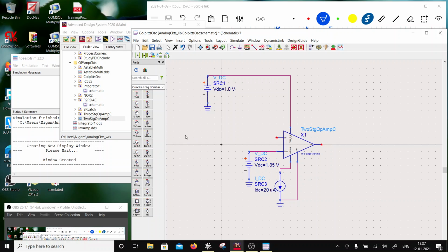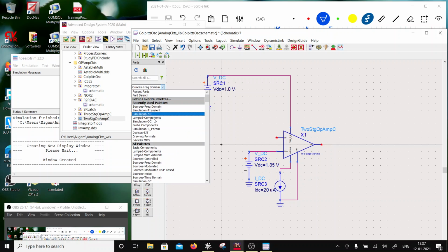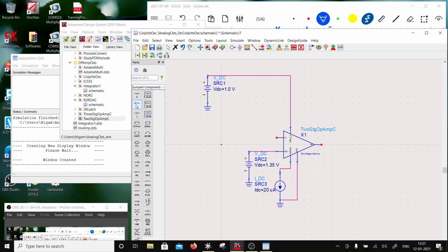CLC. So I'll go here to CLC. So I'll go to lump components. I'll pick up a L, and this L depends on 1/2 pi root of LC. That's how you are going to do that. So L I'm going to keep as 50 microhenry, and I'm going to give a certain loss to it. Let's say 1 ohm loss. Okay, wire wound inductors roughly would be like that.